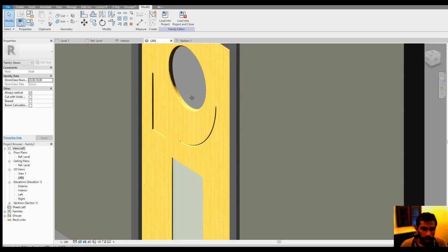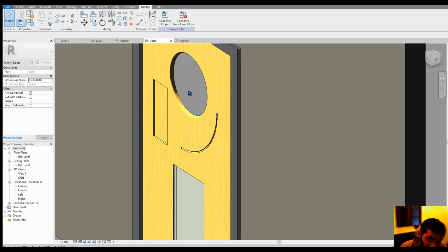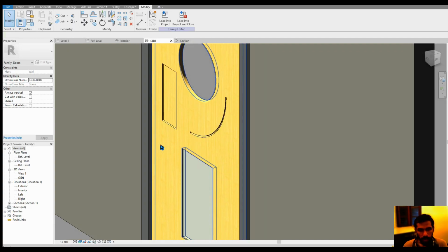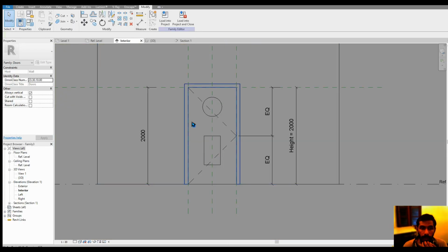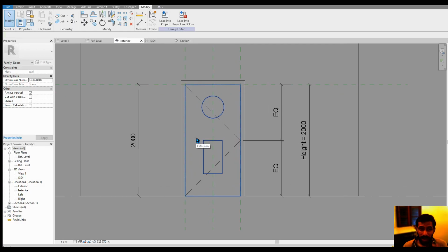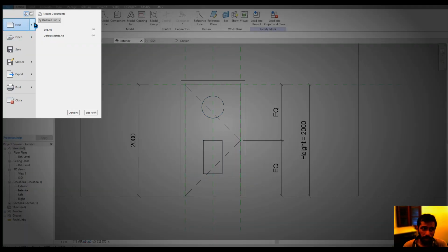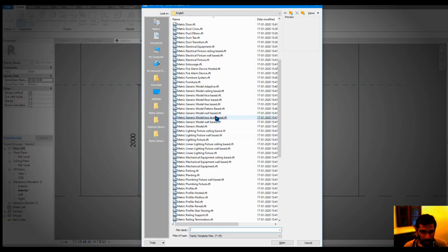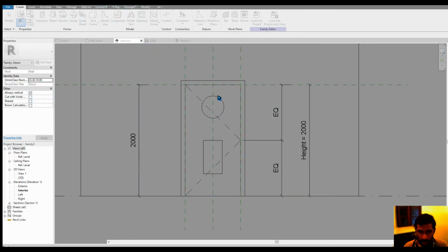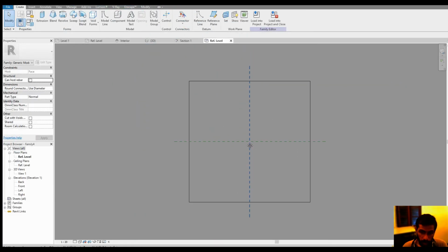Okay, now let me get into the climax. It's already 24 minutes right now. Let me fix some handles right here. Okay, you can model those handles right in this door family, but I like to create a new family for that family, and this one could be maybe a face based family, you can say. And this face will be the door right here.